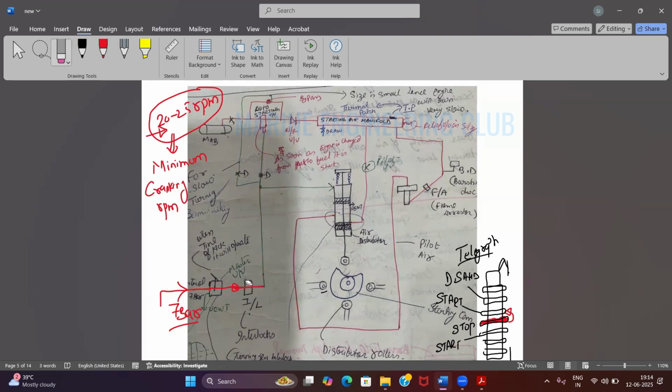And sir, the pilot valve written in green color in the pilot line above, what is that, sir? Suppose I have to do some maintenance on the distributor, so I will close that valve at that time. Otherwise it is always open. During normal time it is always open.